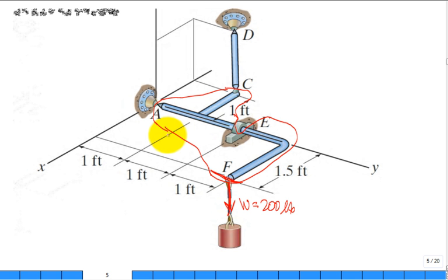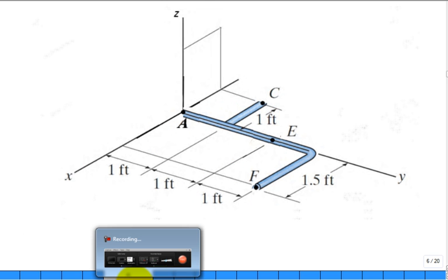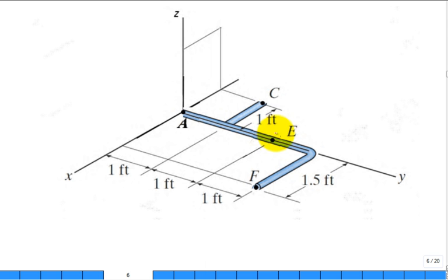Does that help? All right, this is my rendition of that which has now been isolated. Where is the fixture of the surroundings, the ball and socket at A? It's gone. It's just a point A. Where's my bearing at E? It's gone. I just have the rod going through, and then something is constraining it due to the journal bearing at E. Likewise, this has been cut away, and this has been cut away.